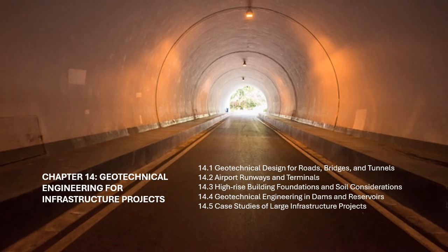Blanket drains. Blanket drains are placed beneath the dam structure to provide a continuous drainage system. These drains are typically composed of gravel or coarse sand, which allows water to pass through without eroding the underlying soil. Blanket drains are particularly useful for preventing water buildup beneath the dam, which could cause uplift pressures and instability.